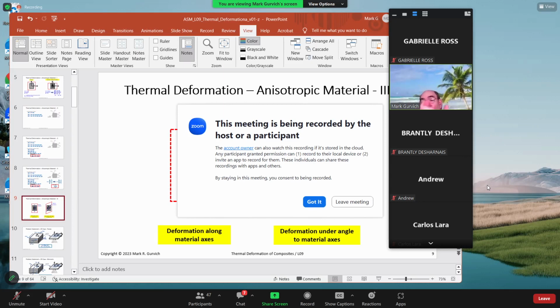So if adhesion between those two layers is relatively weak, boom, immediately a reason for damage. In isotropic materials, it wouldn't be the case. And if we had a 0/90 material, you see my hands, you expand it, there will be no shear as well, because everything will be rectangular after that.